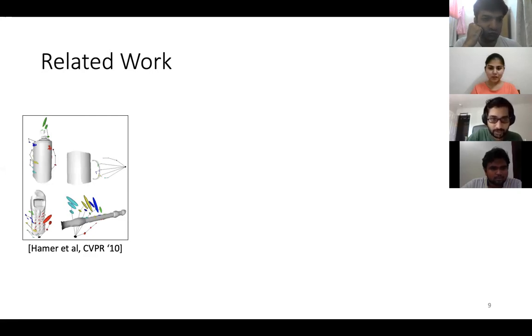For example, you can do 3D reconstruction of the object surface, like what I'm showing here, and simultaneously determine where the hand is, and then say the points on the surface where the hand is close to the surface are contacted points. But that's an indirect inference rather than directly observing the contact. So it's susceptible to errors in this 3D reconstruction of the surface, and also to errors in the hand modeling.